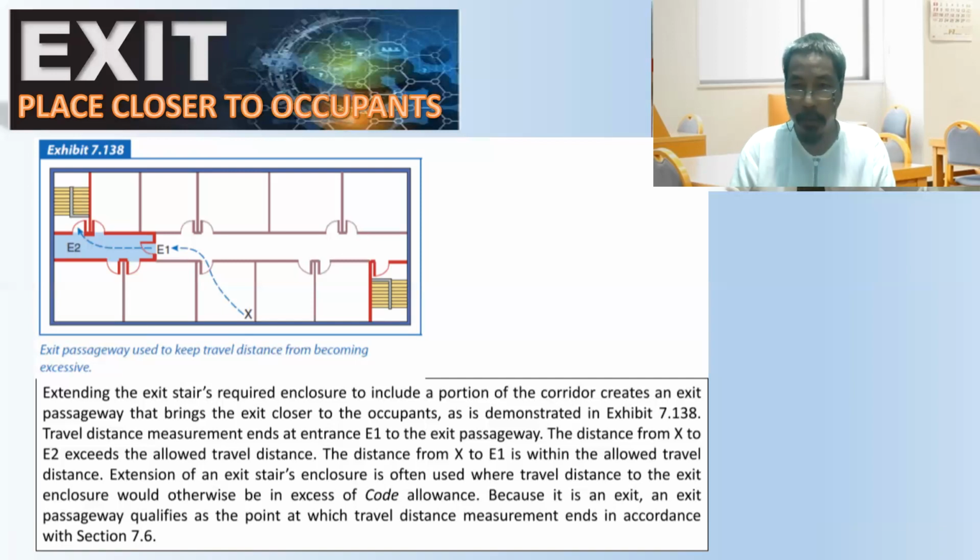explanation. Okay, so in the previous videos, I explained that it is considered now as the exit, wherein that point is now discharging to the outside of the building. Not directly, but at the same safety level. Because of the same safety level and the same condition that exists from point E1 to point E2, the same safety level that you can experience on this exit area.